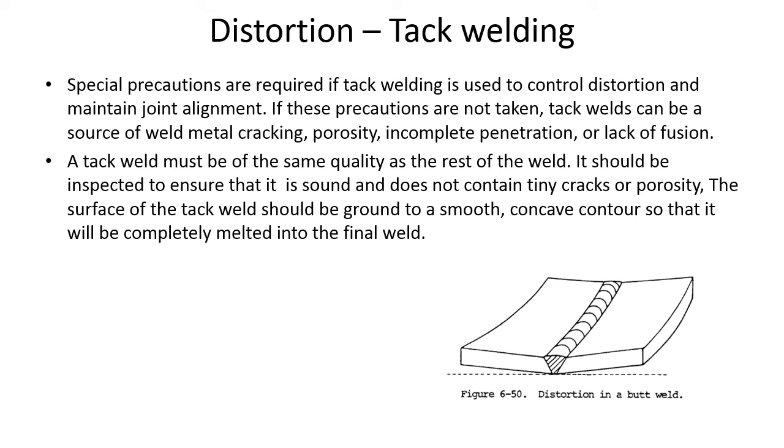So you need to really be careful with your tack welds if you're doing tack welds as a form of distortion control. They need to be high quality. You can't have just anybody tacking things up and leaving slag or dirt or whatever you've got in there. Porosity, if you've got that, you need to grind that out and fix it. Incomplete penetration, lack of fusion, those also need to be fixed, because, in a bigger philosophical discussion, what happens at the bottom of the weld, it'll carry up. So if you've got problems in that tack weld in the root, it'll follow you all the way to the top, whether it's cracking, porosity, whatever.